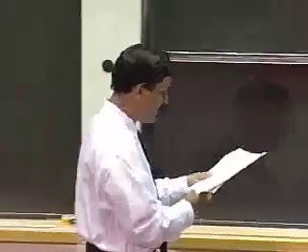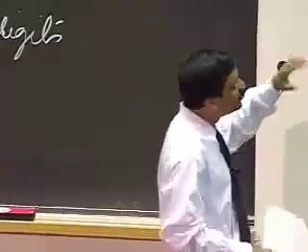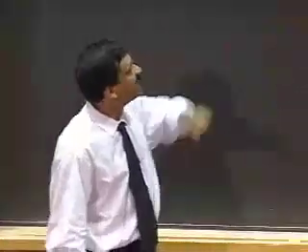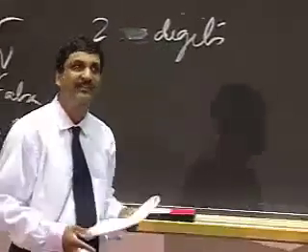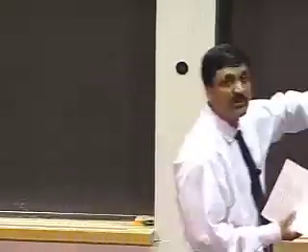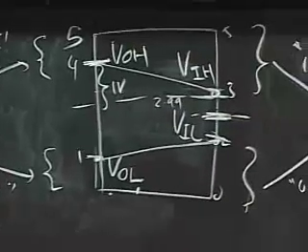So what we have here is a discipline that we've agreed to follow, where senders are held to a tough standard and receivers are held to a different standard, so that I allow myself some margin for error. And it's up to you as a designer to choose ranges for the forbidden region.